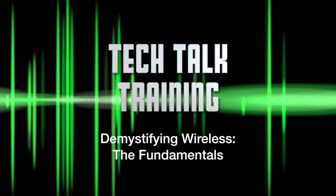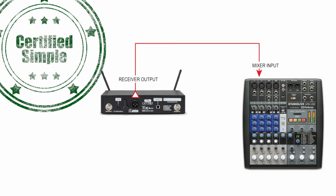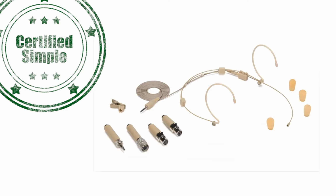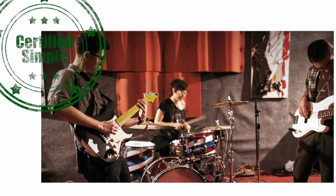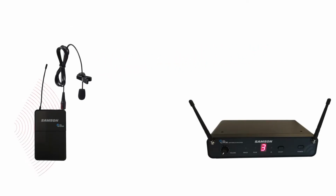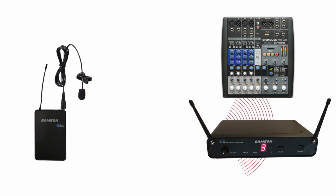Wireless systems are simple to implement. They consist of three fundamental ingredients: the input source, the transmitter, and the receiver, the output of which is connected to a mixer channel input. Whether the input device receives a signal from a lavalier, headset mic, handheld mic, guitar, bass, or other instrument, the wireless system simply receives that signal, typically via a cable. Then the transmitter converts and transmits that signal wirelessly to the receiver, which is connected with a cable to the mixer's mic or line input.